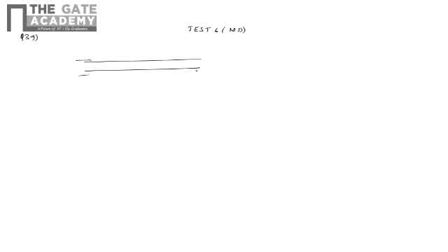So you have bearings at the two ends and you have a rope sheave here. At the cross section there are two loads. If you look at the loading, it is 15 and 15 kilonewton. The resultant of these two is basically 30 kilonewton with no torque because it balances out, right? The moment here cancels at the center, so it's only 30 kilonewton. So 30 kilonewton of load is acting at the center, and let's call this A, this B.